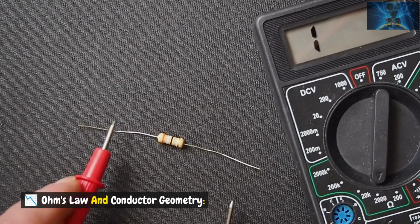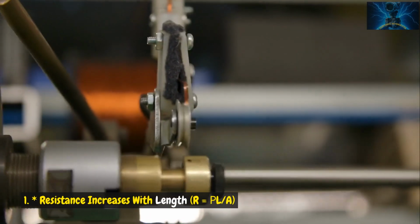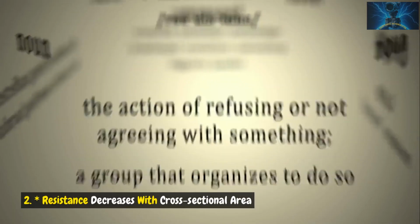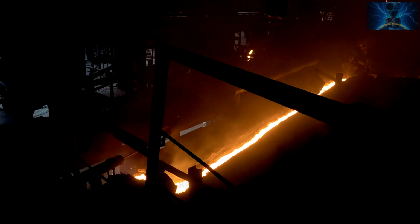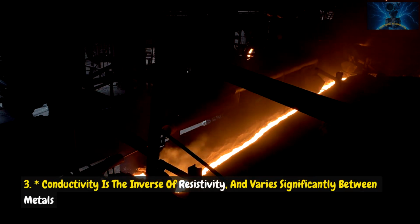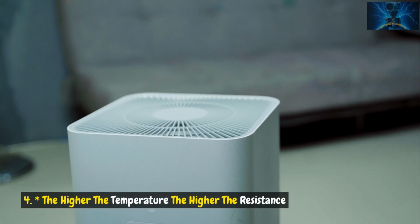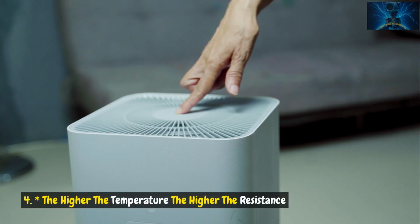Ohm's law and conductor geometry. 1. Resistance increases with length, R = ρL/A. 2. Resistance decreases with cross-sectional area. 3. Conductivity is the inverse of resistivity and varies significantly between metals. 4. The higher the temperature, the higher the resistance.